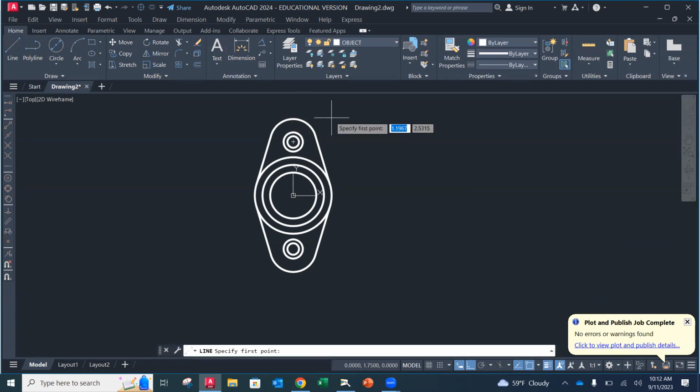And then you kind of saw what happened. You got to activate it. You might have to go back over the top of it. But notice when I run over, this green line appears, that means if I snap anytime now, it's going to be on that line, which means I am in projection on that point. This will only activate if you have quadrant as one of your running object snaps. If you don't, go and set it, because parts like this, it comes in handy.